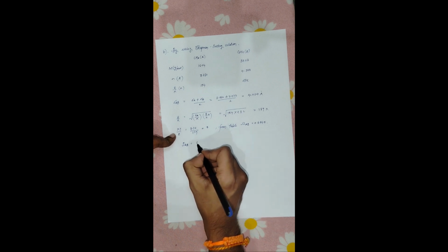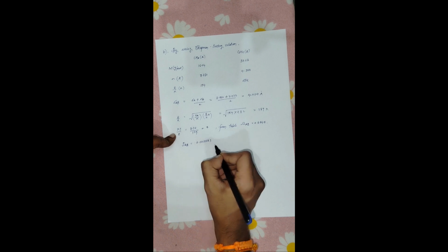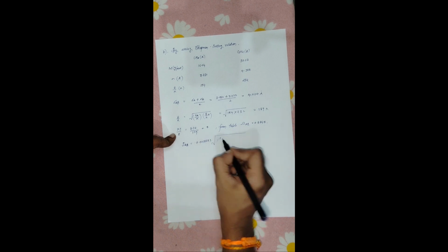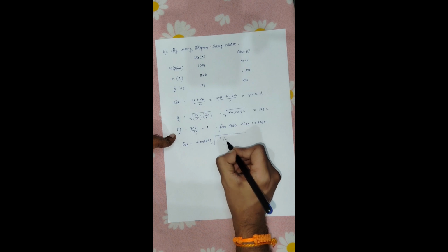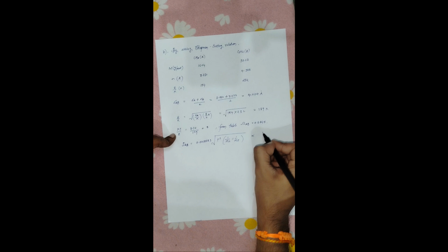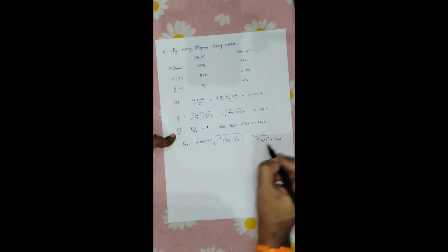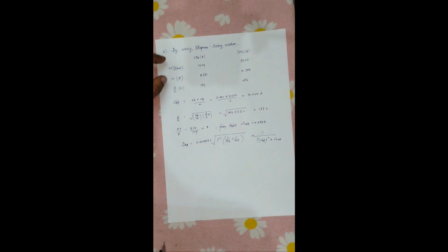So what it is, 0.0018583 T cubed, square root of 1 upon MA plus 1 upon MB, into 1 upon P sigma AB squared into collision integral AB. So we have all this data from here, and simply we have to substitute the data and get the value of diffusivity in part B.